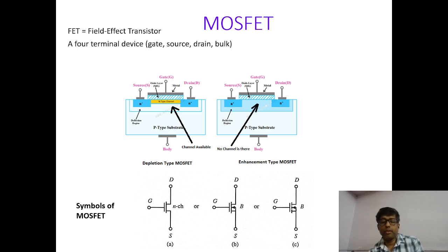Okay, as the positive charge is induced in the diffused channel due to the capacitive action, the induced positive charge reduces the channel conductivity. A portion of the channel is depleted of carriers. The effective depletion of majority carriers in the channel justifies the name depletion MOSFET. Clearly the drain current falls as VGS is made more negative. Okay, we can observe that.